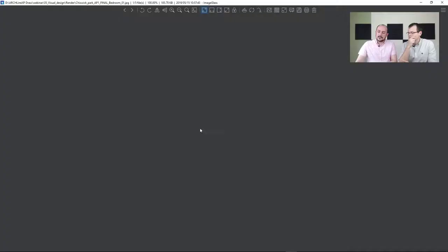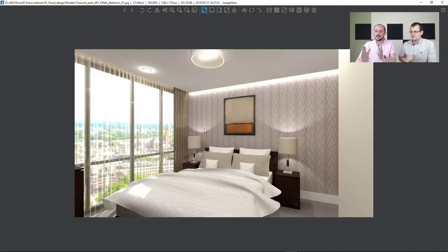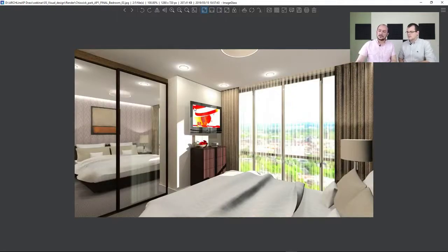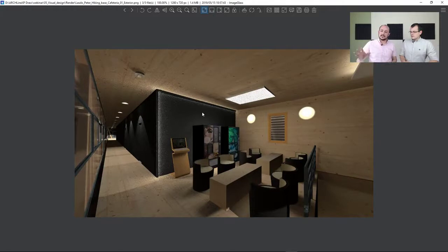So we can see that there are a few examples for one sort of final result with one sort of background, one sort of light setting, and from a different view. We actually used a lighting material here. ARCHLine hosts an emissive surface. You can use that. The example that I wanted to talk about is the different quality settings. Now, this environment was intentionally designed to be less lit, and it has a lot of what we call expensive light sources, because those are not just simple spots, those are surfaces. Surfaces are more difficult to render.